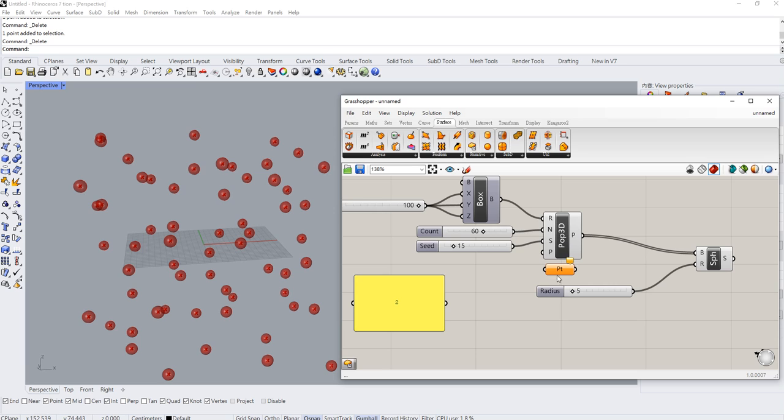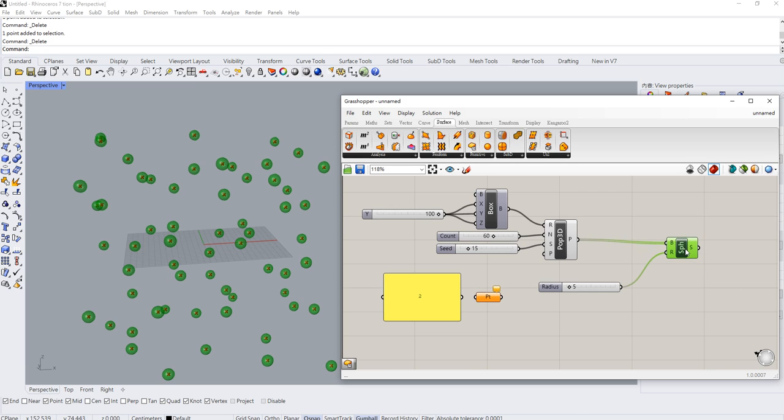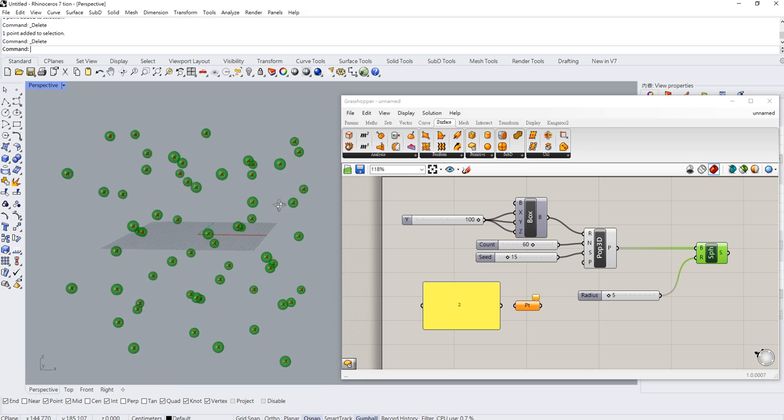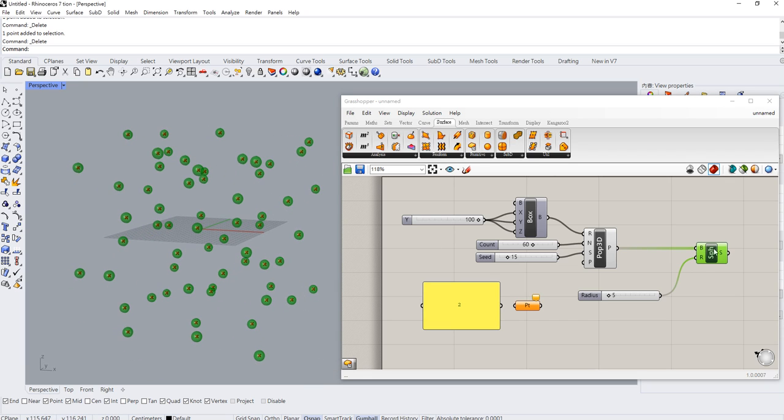So that's your first little script inside Rhino Grasshopper. The logic is, first, we use Populate 3D to generate random points. Then we have to create a region, basically a box. We create a box as a region and input the region to this Populate 3D. And Populate 3D will help us generate multiple points inside this box. Finally, once you generate multiple points, we can use these points to generate the spheres. So that's the idea of how we do this little script.